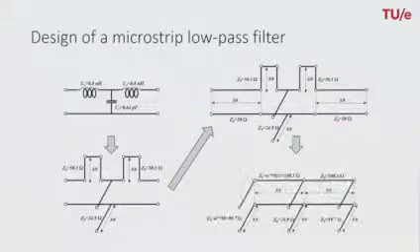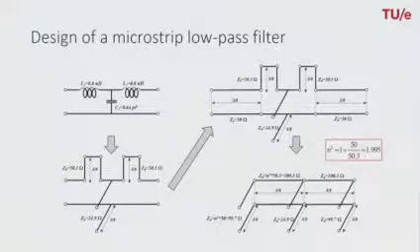By doing that, we transform this transmission line circuit into this circuit where we have three shunt stubs which are connected through two lambda over 8 lines. And the specific values of the characteristic impedances of the stubs and the transmission lines can be calculated by using the value of n squared and by applying the equations that we have just shown.